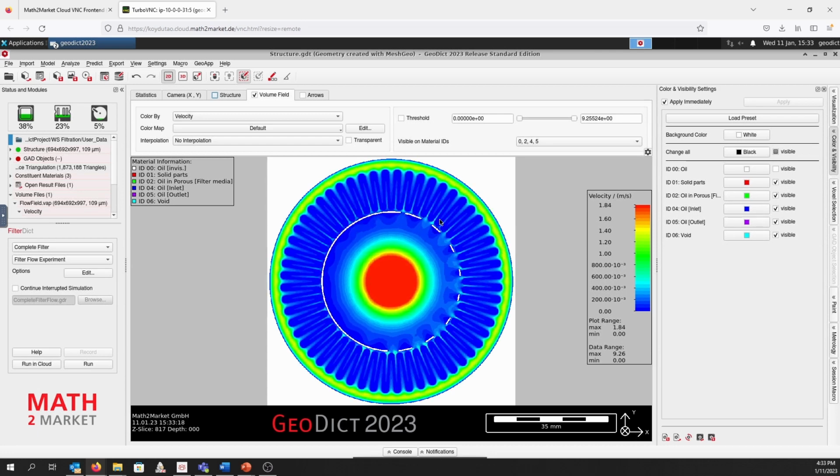And we see exactly how, for example, the structure rotates through the netting inside and how the velocities change throughout. This is one very good control mechanism to see if each of the pleats has flow inside, so we don't have any pleats which are stuck together due to the voxelization method and then are clogged.